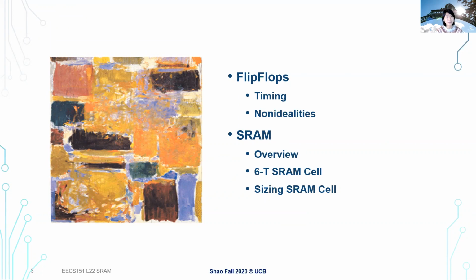You may notice we talk about two very important basic components. Whenever we get to any storage element, you will see a lot of similarities when we get to the SRAM cell. Part of the discussion there is that there are different transistors, and we need to make sure that our SRAM can be read and accessed correctly, but also written correctly. We also need to size the different transistors appropriately to make sure it performs the right function. So we'll also talk about some of the sizing constraints in the SRAM part.